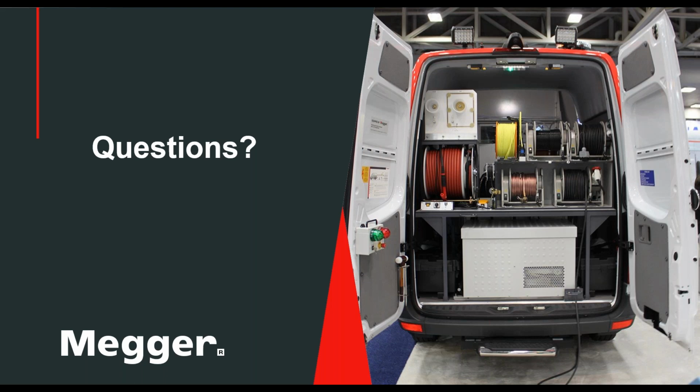On shorter cables, we are typically maybe within 1 or 2 feet with a TDR. But even if you are 10 or 20 feet off, it's not a big deal because you do pinpointing afterwards. So the expectation should not be that because I don't know the velocity, I cannot use the method. That is an incorrect assumption.